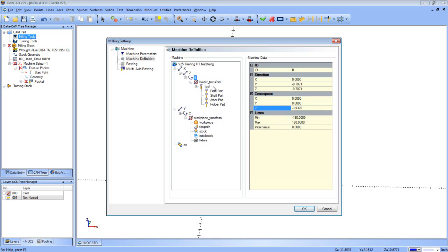Now the B-axis, this is the one we want to take a look at here. And this is the one that we want to set up. And you can see these numbers that are in here. And this is where you want to put those signed numbers. So we're on B. And you can see that the Y is a minus 707 because that one's rotating but not the tool. It's just kicking it on a tilt. And the Z is the minus. Remember, it was cocked in the Z and the Y.